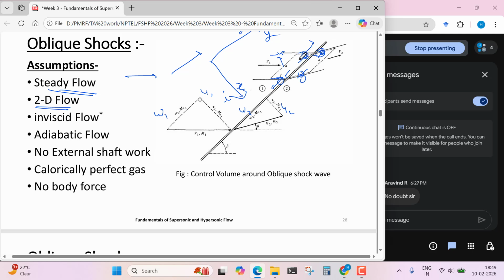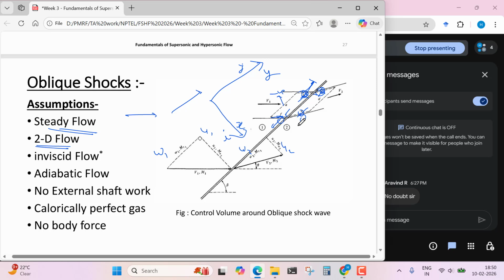So whenever we take the dot product of velocity and surface normal, for the x momentum, it will be 0. V dot dS will be 0 here, because velocity will be tangential to all these surfaces. So we have to consider only two surfaces, A and D.